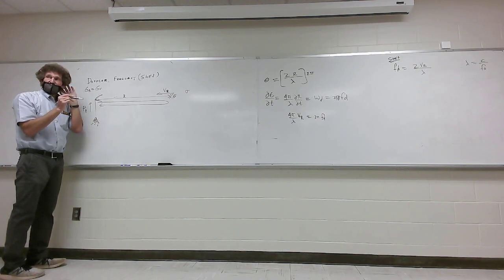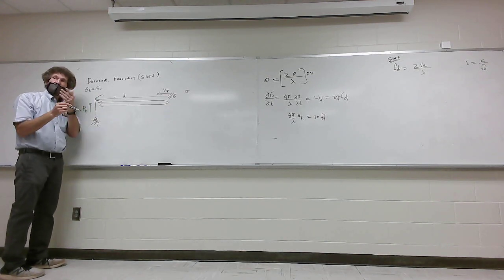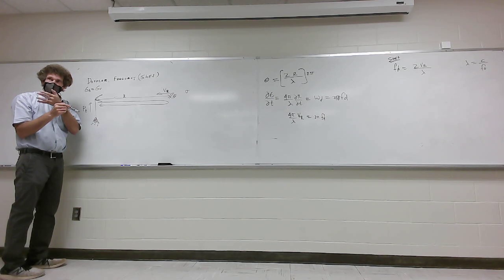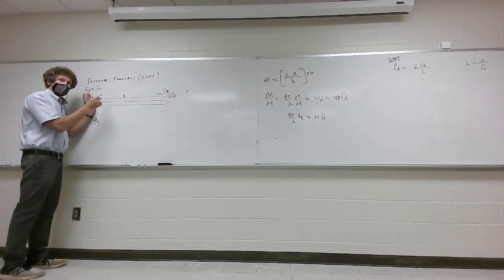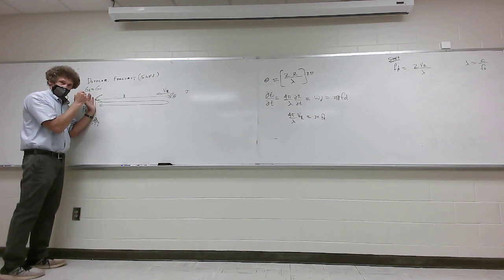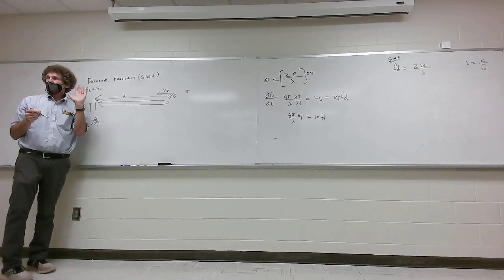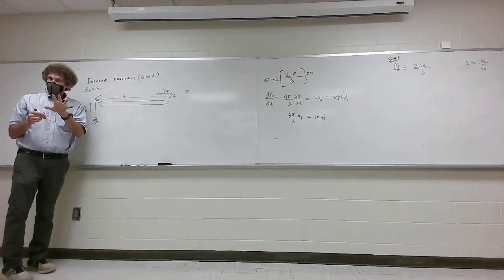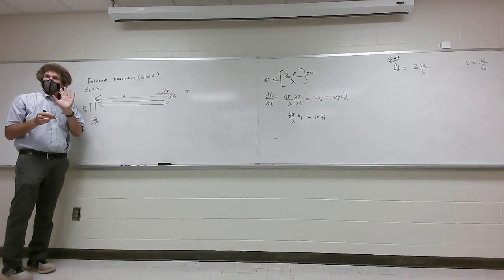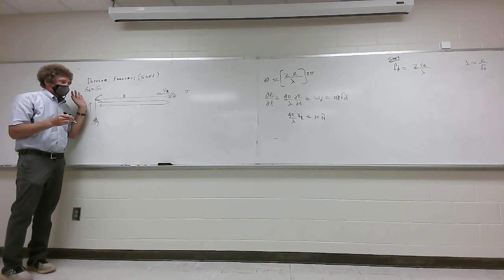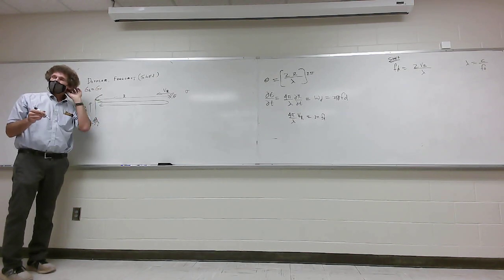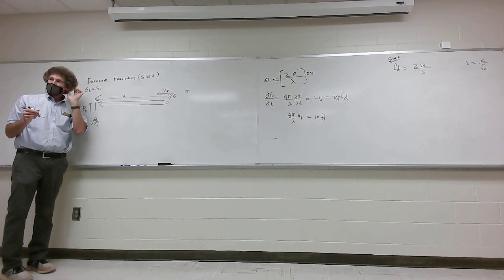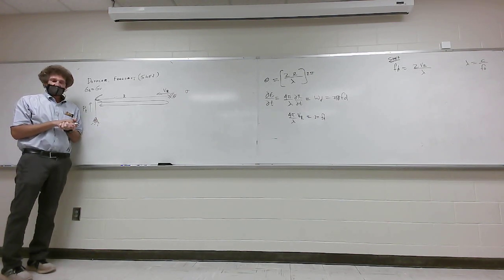You send, you listen, send again, listen. It's like you're listening for echoes. You follow me on this, class? If you send too quick, then you don't know which transmission the echo came from. So there's something called a maximum unambiguous range. These are things that I'm going to get into slightly to let you know how this is calculated. But for the most part with basic radar, you transmit and listen, transmit and listen, transmit and listen. And think of just echolocation in the most basic sense.